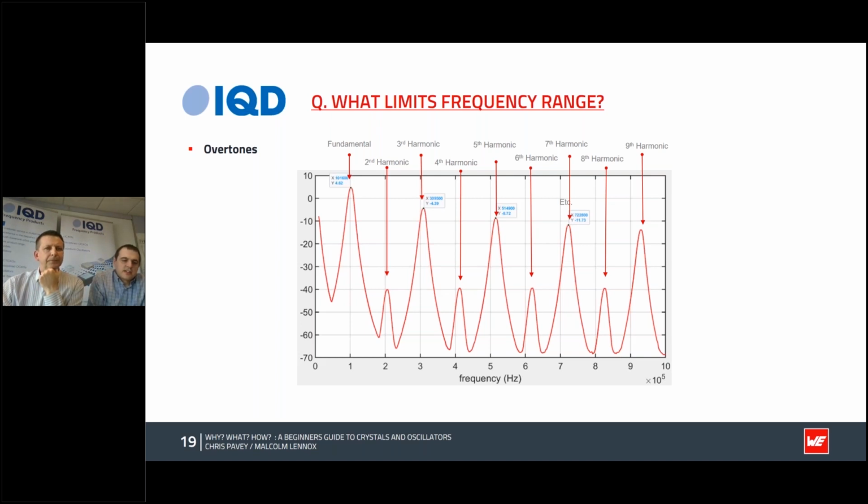The oscillator circuit is specially designed to operate in these modes by using a high-pass filter to block lower harmonic modes. Higher frequency crystals are typically produced in this way, but in general, they will still be within the megahertz range.